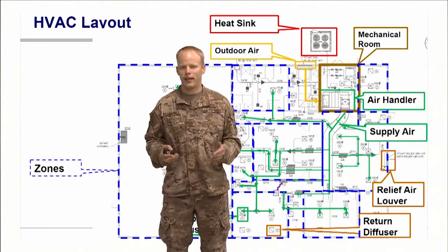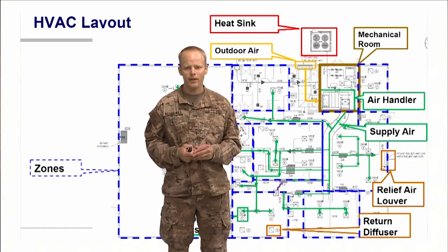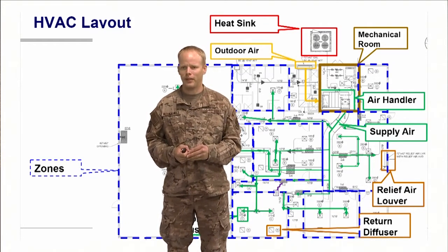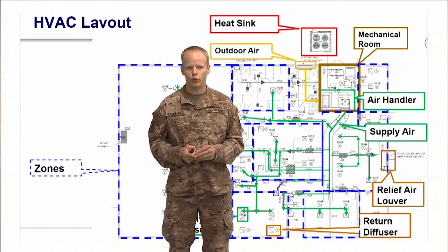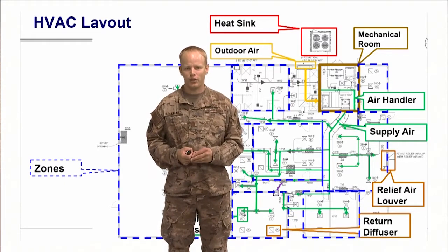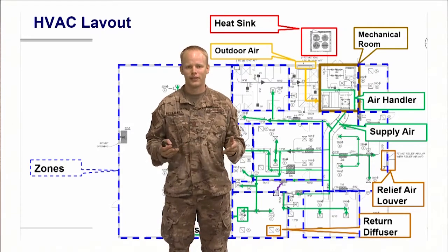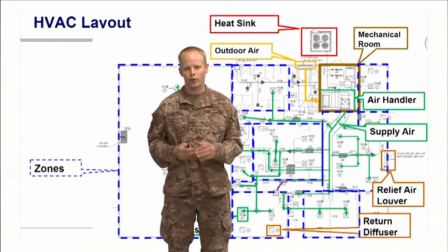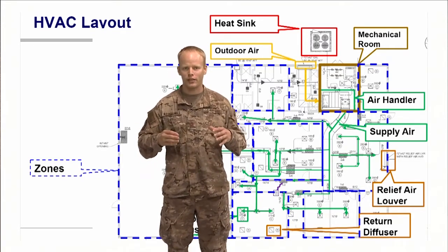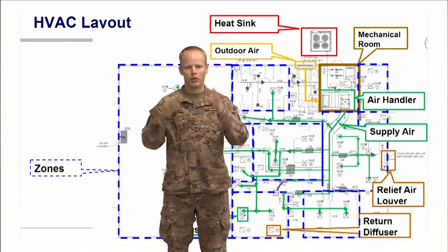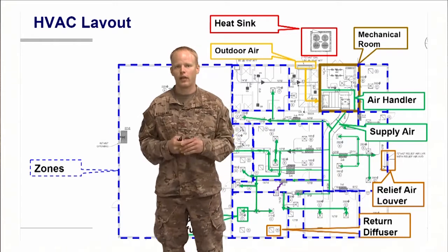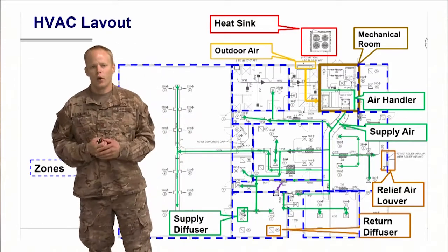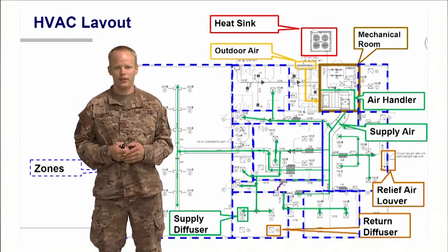One example that one of my buddies at IMSC sent me was a building, I think it was actually at Kirtland, where the roof was basically inflated like a balloon, and the guess was because it wasn't balanced between the outside air and the return air. So they pressurized it. The roof membrane wasn't constrained with rocks on top of it, so it ballooned, it inflated. We typically don't like our roofs to inflate unless it's one of those football training centers, so hopefully that was accounted for in your design and your startup.